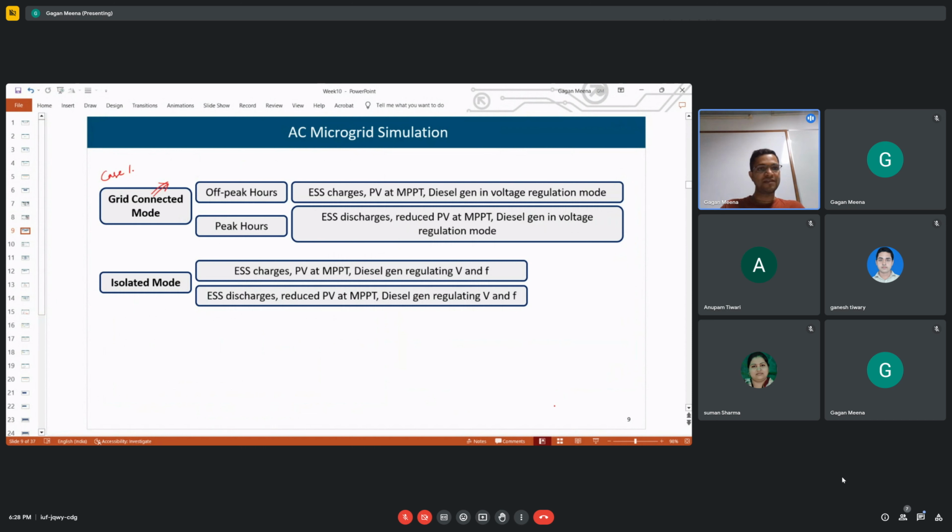And the LC filter which is connected in series is used to reduce the switching harmonics produced by the converter. Then the shunt one, the second one, which is connected on the load side, behaves as a pure sinusoidal voltage source. Because it is connected in shunt, it provides a low impedance path for the harmonics. So harmonics will flow through that and will not flow to the grid side. Correct?